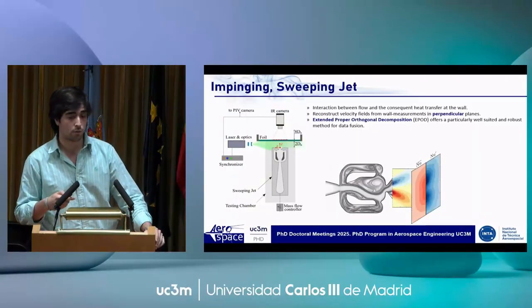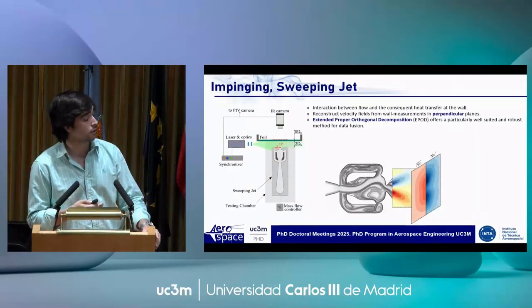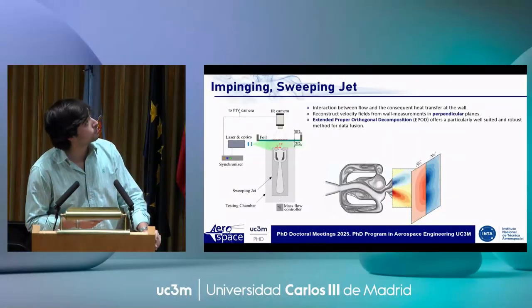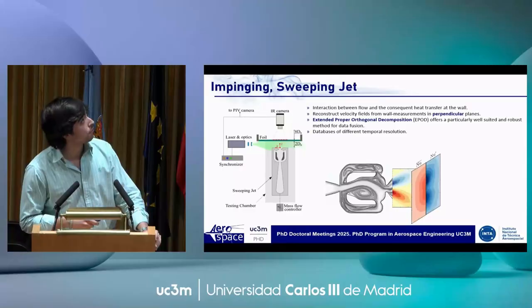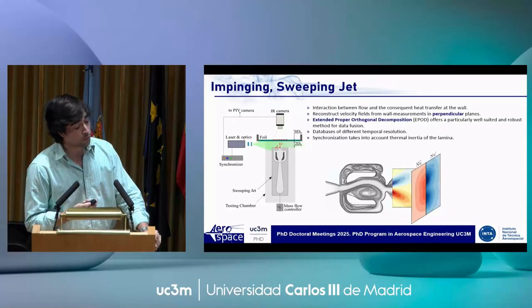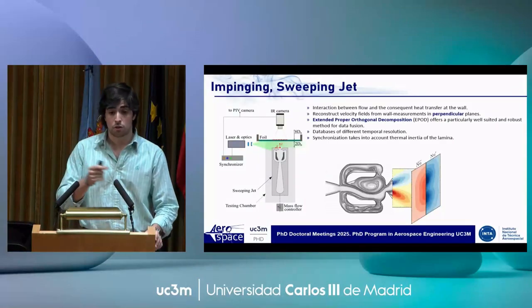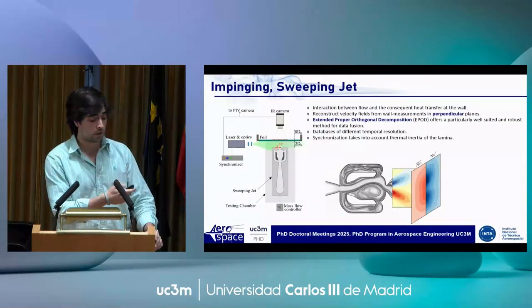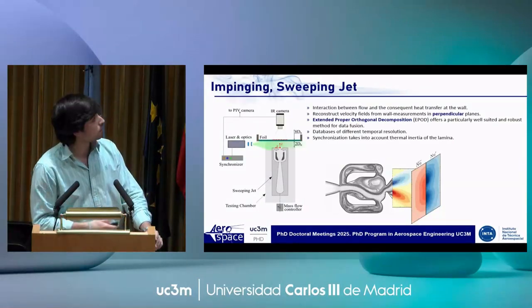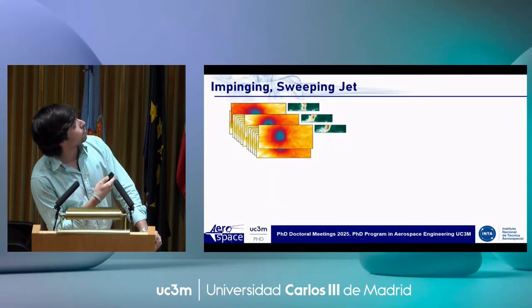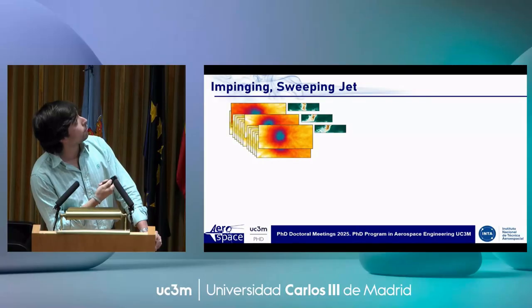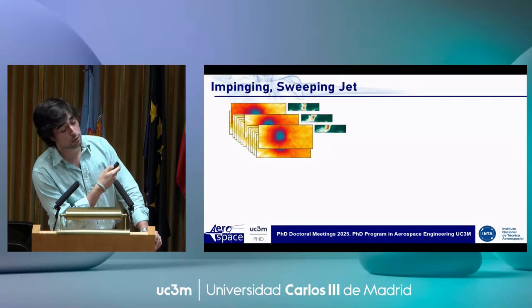In this case, we use fields instead of fast speed probes. So we use databases of different temporal resolution, of different fidelities, and these are synchronous. Although one of them is non-time resolved, there are 22 snapshots, for example, of Nu per each snapshot of velocity. We have many more snapshots of Nusselt than we have of velocity, but for every 22 snapshots of Nu, we have one snapshot of velocity.